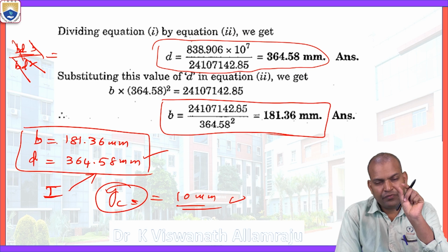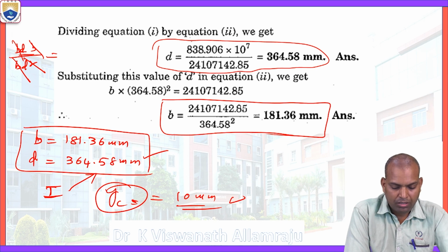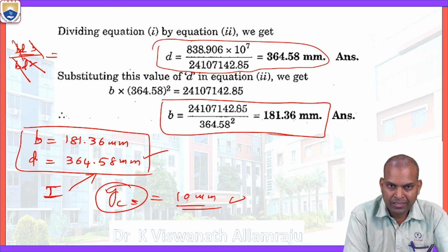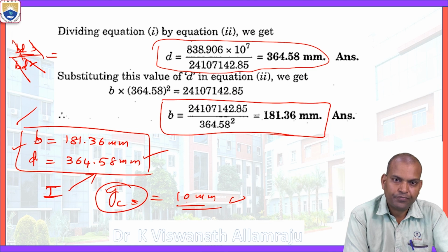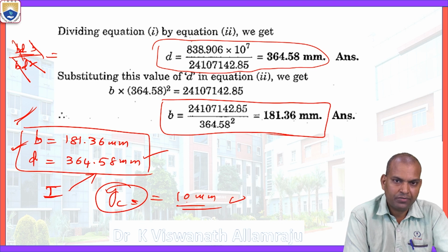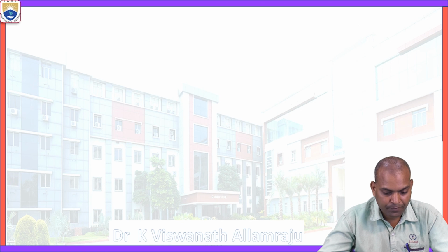So if you want a particular deflection, a very important design characteristic, we can use this problem for calculating it. If you want to minimize the deflection, say 2 millimeters, let us use 2 millimeters, then you can know the geometry of the beam. If you want 1 millimeter deflection, we can know the depth and width of the beam, especially for a rectangular cross section.